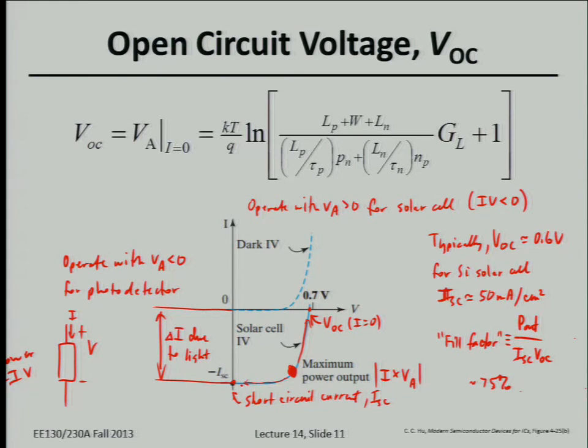Okay? And that's kind of a practical challenge for solar cells today, because you usually have many solar cells connected either in parallel or in series, and due to variations in the manufacturing process, this optimal operating point is actually slightly different from one cell to another, and that makes it kind of hard to get the most energy efficiency out of an array of solar cells.